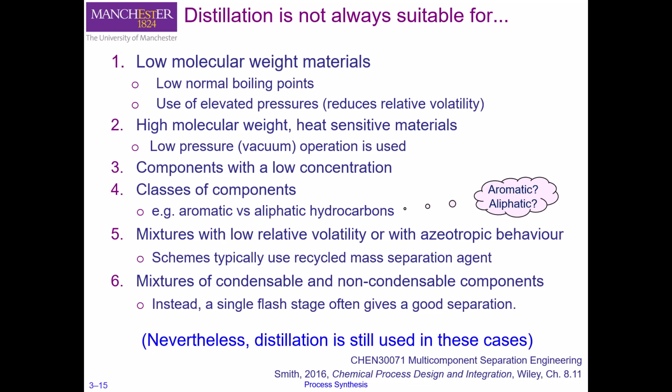Secondly, large molecules are sometimes sensitive to high temperatures, such as their own boiling points. It means that if you heat them, they might degrade or decompose before they actually reach their boiling point. One way around this situation is to do distillation under vacuum, but as you can imagine, vacuum brings additional challenges and costs in terms of the safety of the operation, but also the capital cost, because you need much thicker walls and special materials for vacuum.